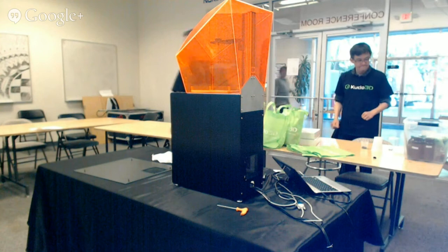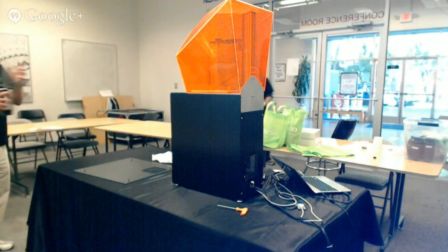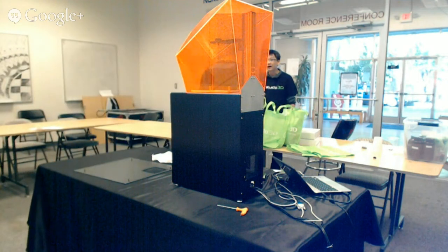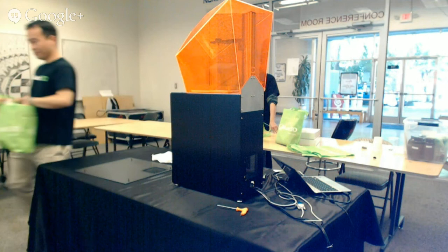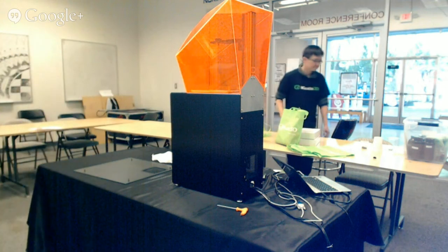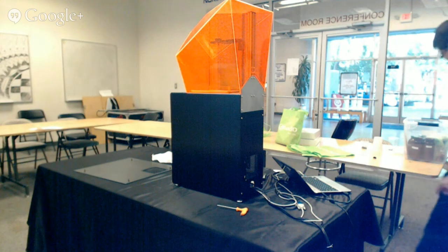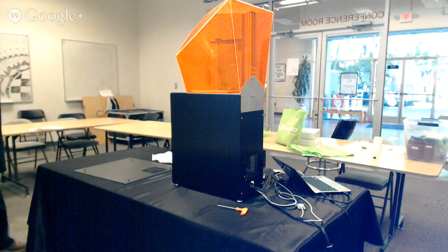Essentially, at some level, you increase the amount of initiator, and it increases both the depth and the speed of cure. And then at some point, the depth of cure starts to go down, and the speed of cure kind of straightens out, flatlines, because then there's so much initiator in there that it's also blocking. And then you've reached some maximum initiation rate.